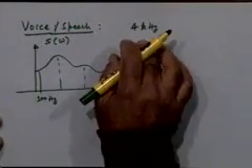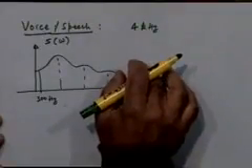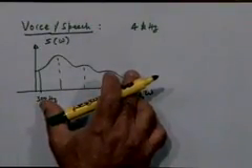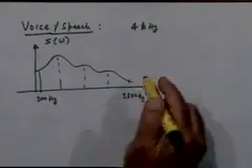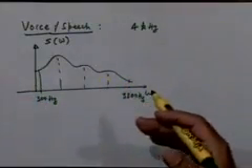So the original point that I was making, from which we digressed, was that bandwidth is an important resource. The voice signal has a bandwidth of about 4 kilohertz, but it does not necessarily mean that the information conveyed by a voice signal when I am talking to you is proportional to 4 kilohertz, or of this order, because this bandwidth is a property of the speech waveform that is coming out when I am speaking.